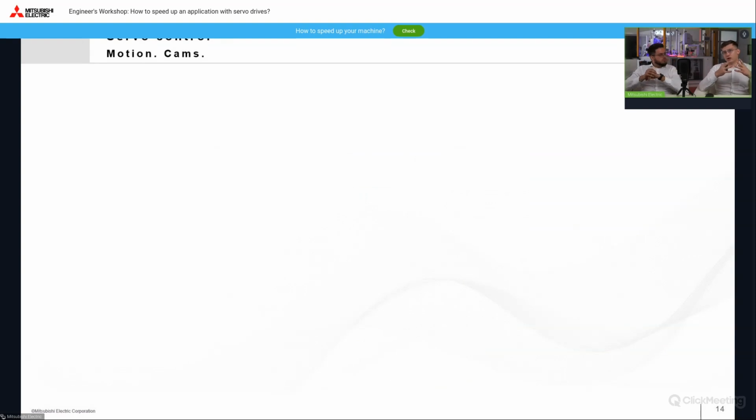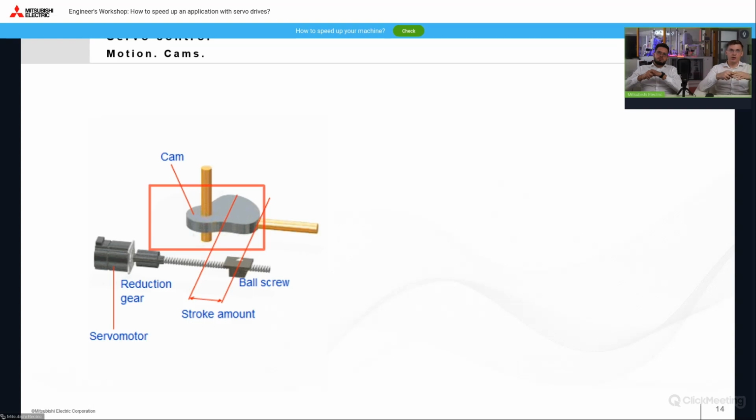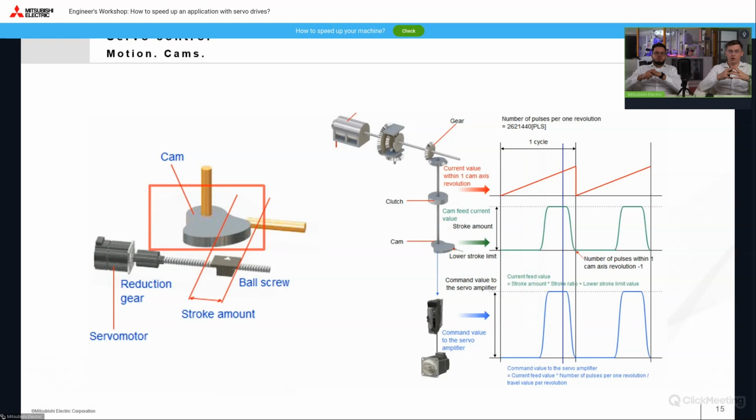Motion allows you to use functions such as the cam, which works on the principle of a mechanical cam, of course. In a cam case, its special shape results in a specific movement profile, for example, linear. Such solutions are used, for example, in the valve train of internal combustion engines, where cams control the operation of the valves. The electronic cam works on an identical principle, only the cam parameters are set directly in the servo program. In this way, we can control, for example, the position of the drive or its speed over time.